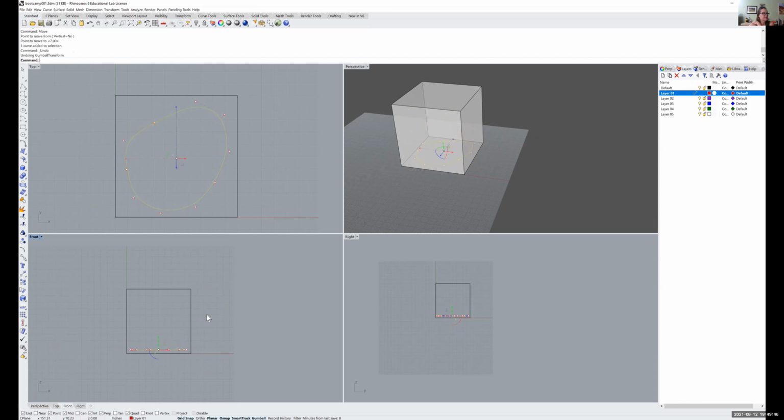Yep. To make the curved lines, which one did you use? I used the 4th one down, the control point curve. Okay. If you hold that down, there's a whole bunch of other options. The second one is interpolate points, so it'll go through those points. Even if you wanted to use a polyline and have it be not curvy, you could do that too.